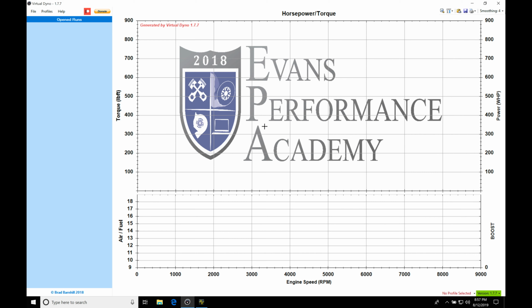We're going to be taking a look at working with our Virtual Dyno software in conjunction with our AEM Infinity tuning. So when we're doing our tuning with the Infinity software, we're going to be capturing our data logs. That's going to allow us to review what kind of changes we need to make to our fuel tables, to our spark timing tables, boost control, idle control, and many other parameters. Now, we can review the data in the Infinity Tuner software. We can also review it in the AEM Data software.